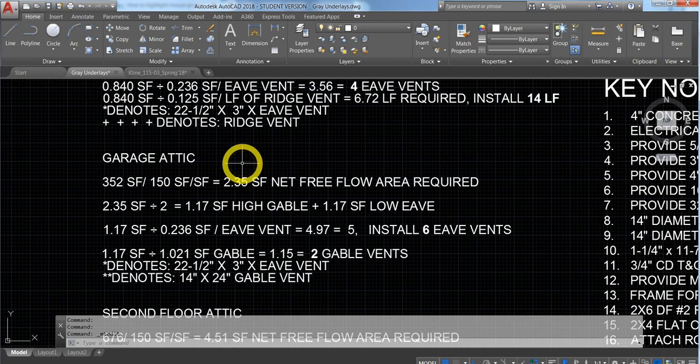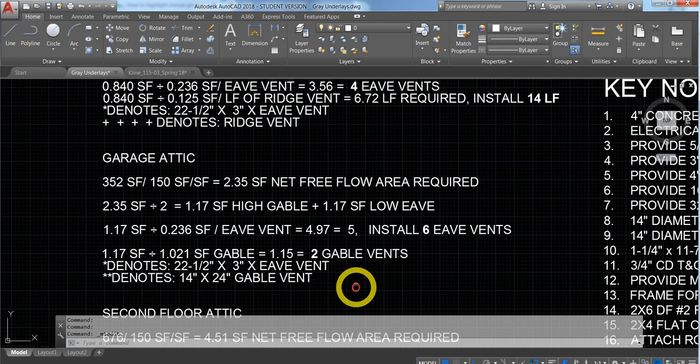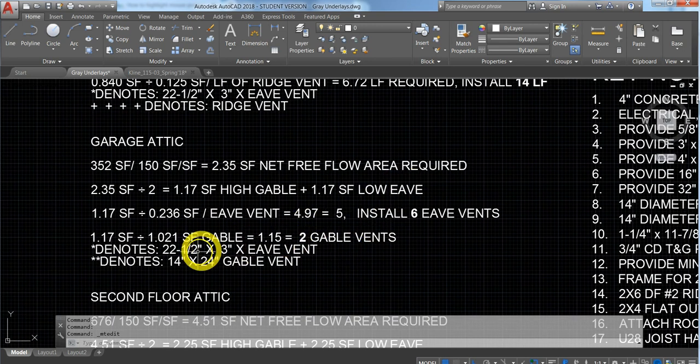And again, if you go to Home Depot, you see a vent. They're usually 4 by 10 on the eaves, and then your bigger one, the one that we're going to use, is right down here. I'm just giving you the vent size, a 14 by 24. I'm doing the cross-sectional area of this to figure out how many of these vents I need for these two areas.